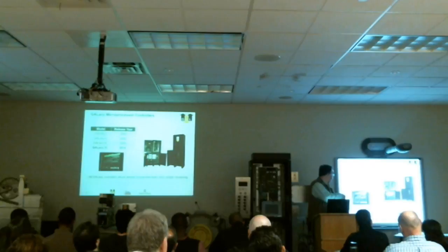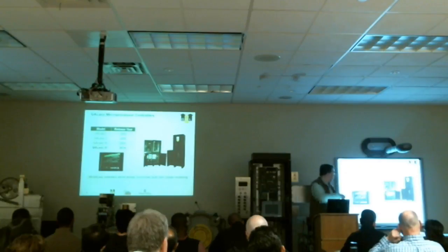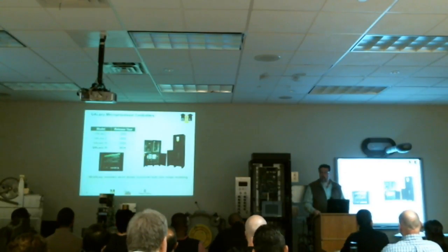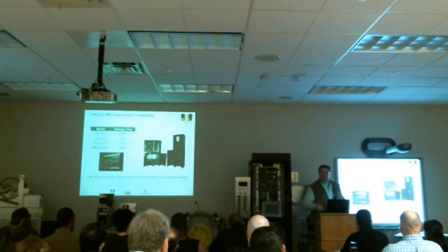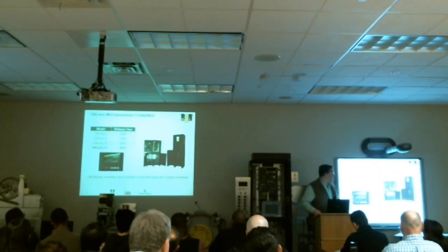So Galaxy 3 and 4 on older versions from the last, I'd say, 12 months or before, when we instituted the fire phase 2 monitoring feature, would require a software upgrade on controllers. So for those of you that get phone calls, especially in sales, customers say, I got a Galaxy from 2006, 2007, 2009. What do I need to do for complying with code door lock monitoring? They would require just an upgraded software from us.